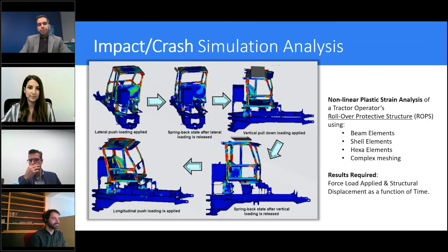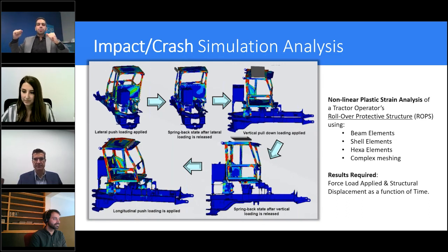In this example, there are areas where we need to do implicit analysis, for example, extreme load, but in a quasi-static way, to see how the roof is deformed. And that deformed shape has to be the initial geometry and initial model for a drop test or impact analysis.